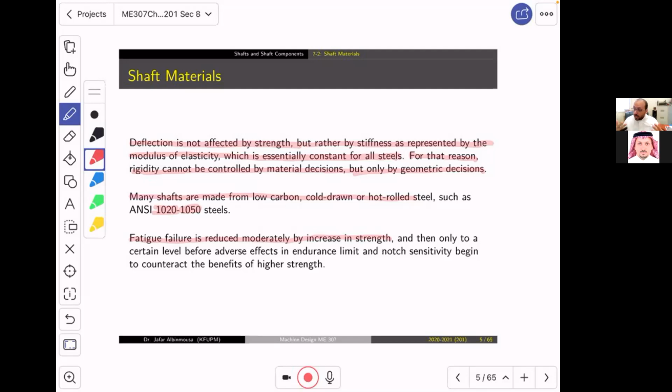Now, what you need to understand, which is explained in one of the sections of chapter 6, I think, is fracture mechanics. Unfortunately, we don't cover this in the material of the course. But what fracture mechanics is telling us is that if you have a crack and the material is brittle and you apply a significant load capable of propagating the crack, in reality the crack might grow in the material, if it is too brittle, at the speed of sound.